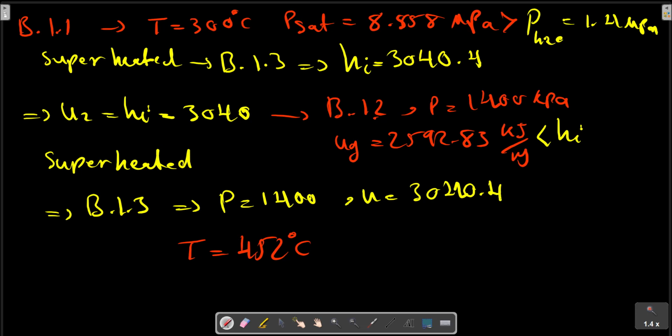This process is adiabatic, but we must examine the two boundaries for work. If we visualize a piston between the steam that is included in the control mass and the steam that follows behind, we readily recognize that the boundaries move and the steam in the pipe does work on the steam that comprises the control mass.